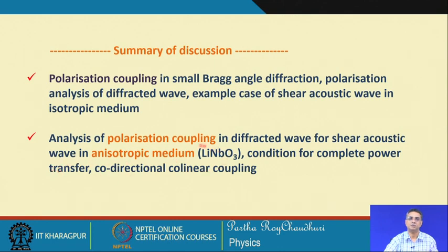This was the case of a large Bragg angle diffraction with co-directional and collinear coupling, and we saw that from this calculation, from this expression, we can determine how much acoustic power is required for complete transfer of power from the extraordinary incident beam to the ordinary diffracted beam in the collinear direction.